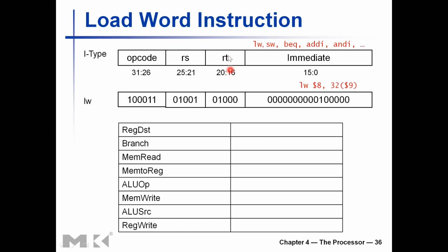We are going to write to that register. We are going to read from this register. What we are reading is the memory address value, a 32-bit memory address value. Then we need to add this immediate offset into that base address value, go to that address in the memory, read, get the result, and write it into this destination register number.